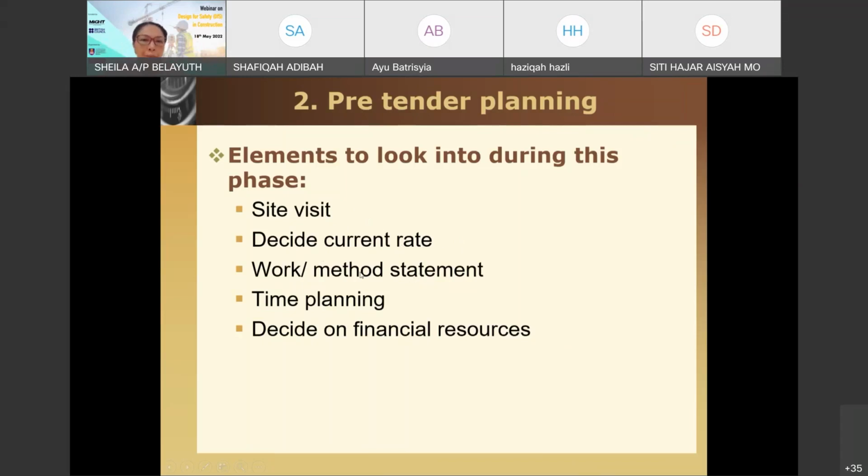Okay. All right. So work method statement. Okay, so what are the ways for us to conduct a certain activity? For example, simple is basically concreting. Okay, there are various ways for us to do concreting. Whether do we want to have our own batching plant, because a lot of organizations, if it is a big project, they just hire the whole batching plant. Okay, so that for the concrete truck to arrive, it doesn't need to leave the site. Okay, so if it involves huge volume of concrete, but if it's not, it is just a simple structure which you think might not require huge volume on the site, then might as well, and there are nearby batching plants. So then it could be using concrete truck only.